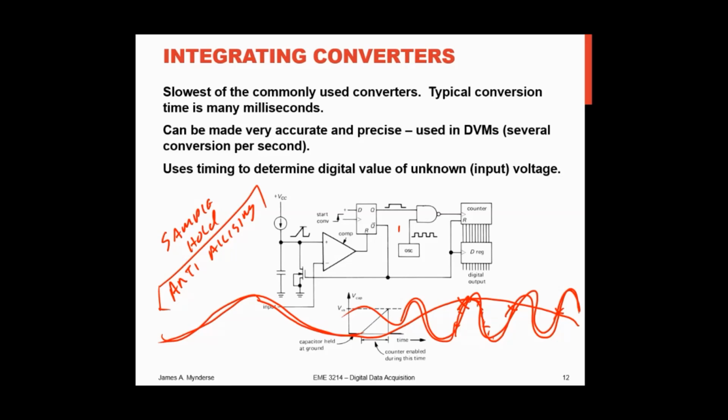An example would be, let's suppose you're an engineer working on tuning a suspension in a car on a test track. You're driving the car, and the test track's got some sine wave surface. That's not uncommon. They have sine waves of different wavelengths cast into the test tracks, and you drive across those at different speeds so you can excite the car at different frequencies. And you may be exciting the car, and something is resonating and bouncing at this high frequency, but because you're testing for hours, you picked a really slow sample frequency to store your data because you don't want to have to deal with terabytes of data.